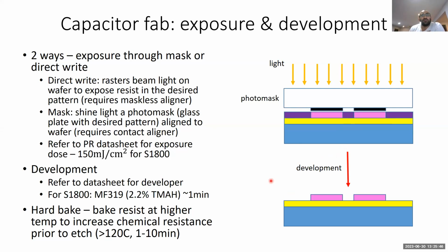And then once your exposure is done, you can develop your resist using a developer. In our process, as mentioned earlier, we use the S1800 series, and from the data sheet, I can look up the exposure parameters and the developer compatibility. Our process ends up using a TMAH developer, MF319, and we develop for around 1 minute. And that's enough to remove the regions of resist that have been exposed